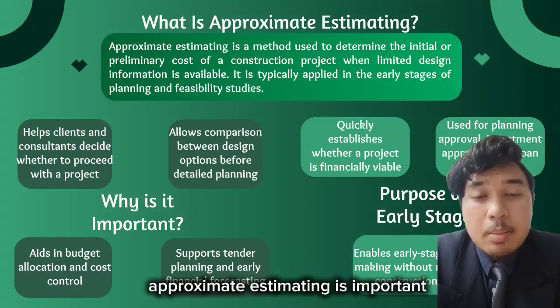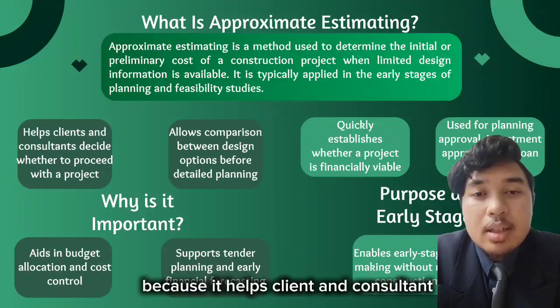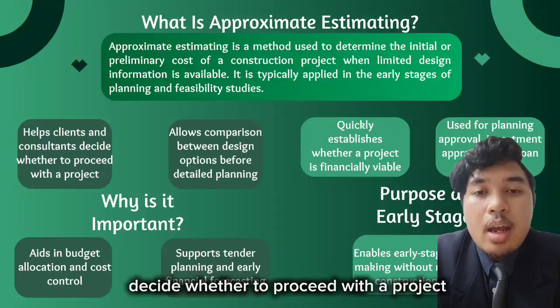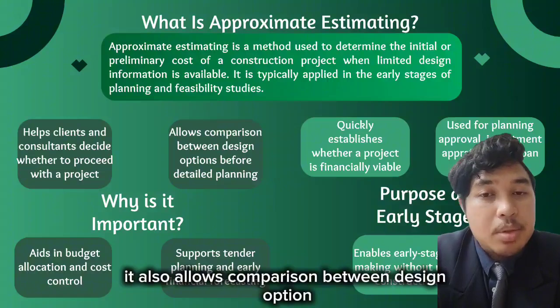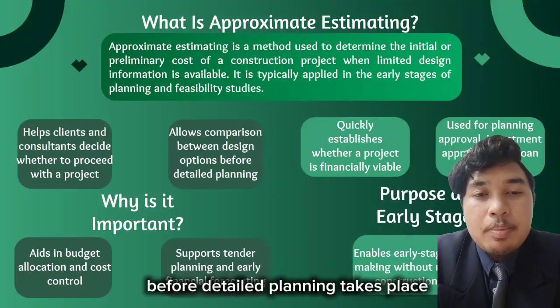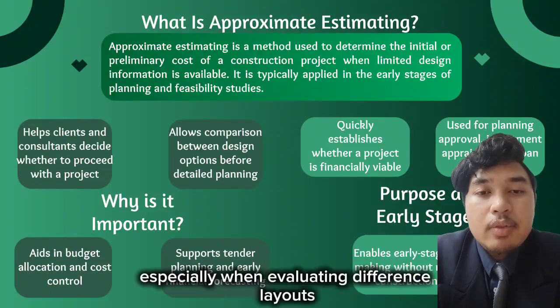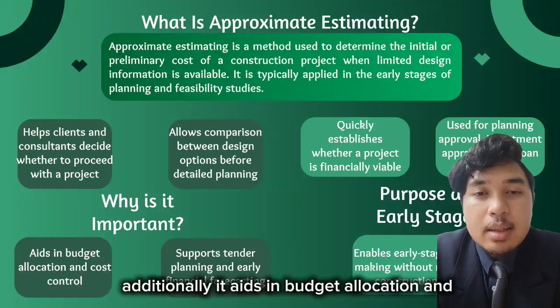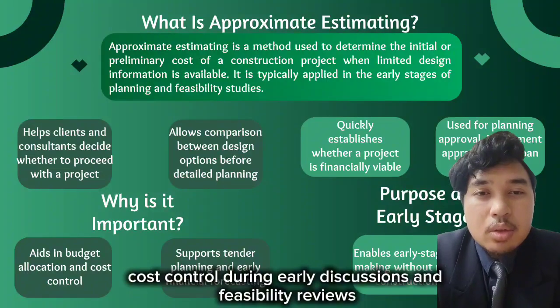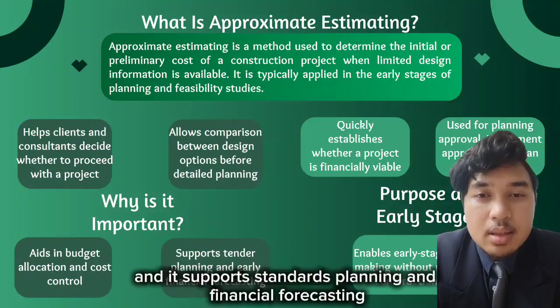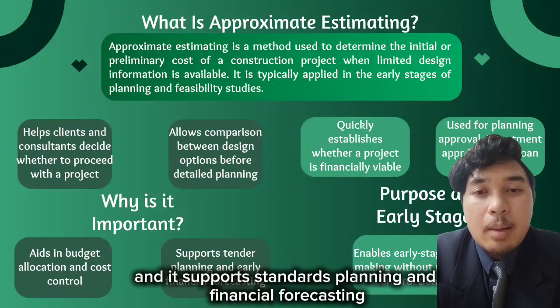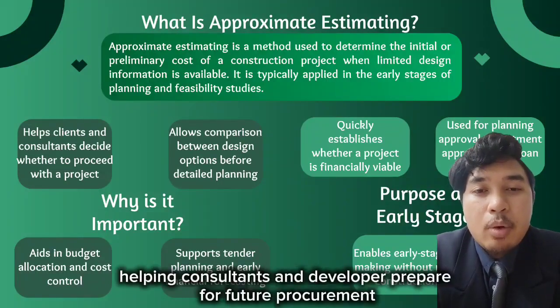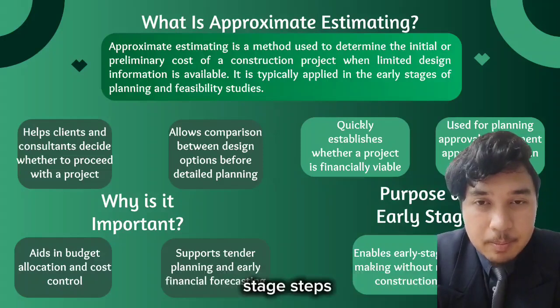Approximate estimating is important because it helps client and consultant decide whether to proceed with a project. It also allows comparison between design options before detailed planning takes place, especially when evaluating different layouts, sizes, or construction methods. Additionally, it aids in budget allocation and cost control during early discussions and feasibility reviews, and it supports standards, planning, and financial forecasting, helping consultants and developers prepare for future procurement steps.